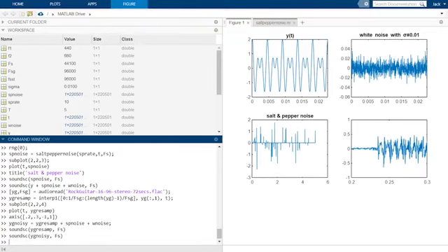A non-saturated amplifier will simply scale the input signal by some gain factor A. But when the amplifier is saturated at some maximum value, we will call clip, only values of the signal with magnitude less than clip divided by A are correctly scaled by A. Values of the signal with magnitude greater than clip divided by A are clipped to have a magnitude equal to clip, the maximum output of the amplifier. So basically, distortion just involves clipping the maximum magnitude of the signal.